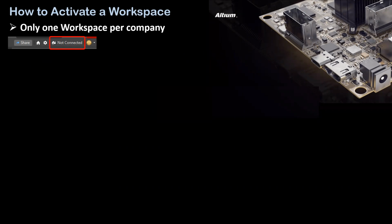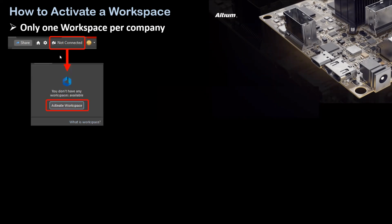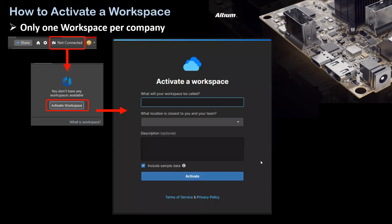If you have not created your workspace, do so. This is how you do it. If you go into Altium up at the top right, you'll see your name and avatar there. It says not connected. If you click on that, it will invite you in to activate your workspace and into the Activate Workspace page.